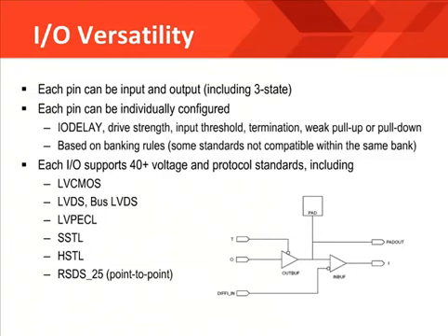These rules apply because each I/O bank shares power pins for each of the input and output pins in the bank. Specifically, the VREF powers the input circuitry and the VCCO pin powers the output circuitry. So whichever I/O standards you group into each I/O bank, make certain that the input pins can support the same VREF and the output pins can support the same VCCO. Now, as an FYI, this is easily planned by using the PlanAhead utility included with the ISE software.